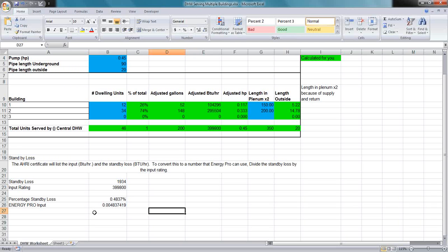I usually only see this, though, in larger buildings, and that's frankly where you're going to get a lot more response from the improvement of these pumps, in terms of the non-residential performance versus the residential performance modules of EnergyPro. For the size and scale of buildings that we deal with, the nuances of VFD and the performance of high-efficiency pumps are not as easy to model and implement. So if you have a project that's dealing with primary and secondary pumps of different sizes and control strategies, go ahead and just talk to us and we'll deal with this on a case-by-case basis.